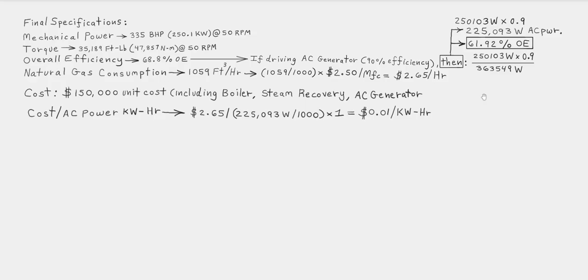So that's in dollars, so that's 1.7 cents, so 2 cents. This comes to 2 cents a kilowatt hour to the customer. And of course, there's going to have to be a profit margin if you're running this as a company. So we could jack that up by, let's say, 200%. So you could still get 4 cents per kilowatt hour electrical power generation to 7.5 houses.